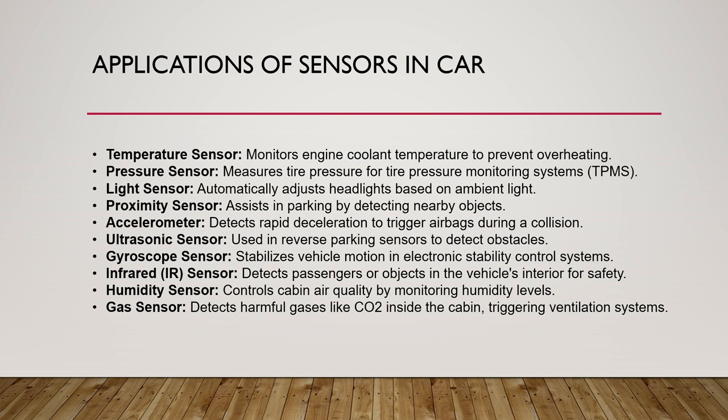A temperature sensor can monitor the engine coolant temperature or the radiator temperature to maintain the temperature of the engine within a certain range, like up to 100 degrees Celsius or 120 degrees Celsius. Talking about pressure sensors, they are mounted near the axles of the tires and monitor the pressure of the tires for all four wheels. When the pressure of one wheel is low, it shows a beep on the dashboard.